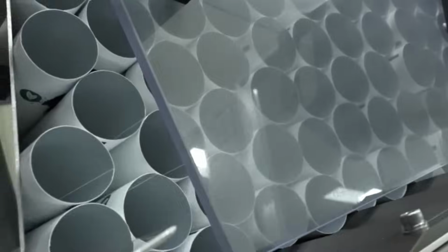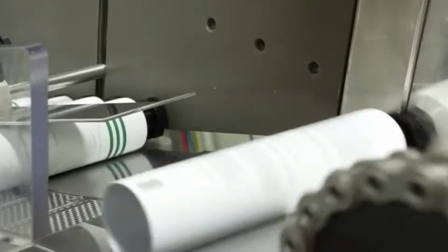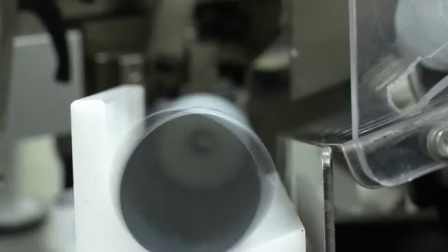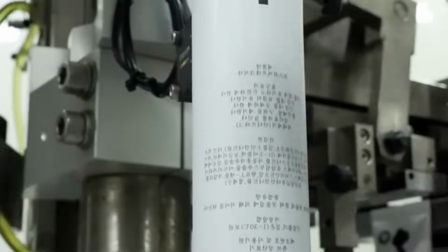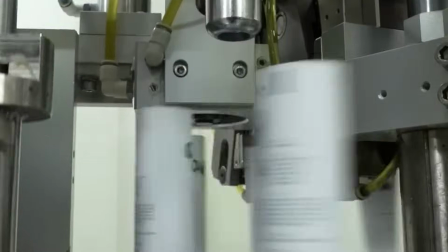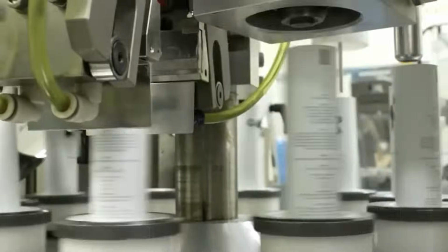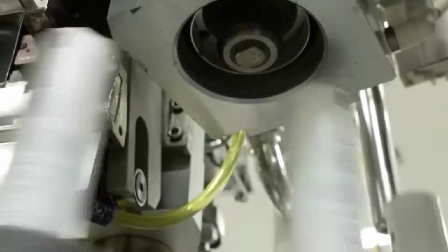Rheological properties are tested in real time using rotational viscometers. Samples from each batch are drawn via sampling ports and analyzed for yield stress, viscosity at shear, and thixotropy to confirm product performance. pH levels are measured with inline electrodes during mixing, typically targeting a range of 6.5 to 7.5, depending on the actives used.